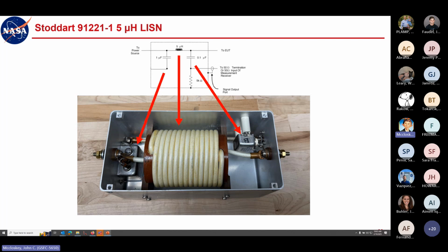the first outlet in the chain, and then those outlets in your office and maybe that whole group of offices in that corner of the building are ganged together, daisy chained together, running off of a very high common source impedance. That's where this kind of thing makes a bit more sense, where you have a very high common source impedance, where whatever noise you generate is going to be seen on that power bus by everybody.